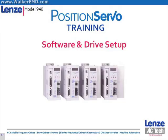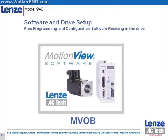In this section, we will discuss the Motion View on Board (MVOB) programming software and the basic position servo drive configuration. Position servo drives feature Motion View on Board (MVOB) software. The MVOB software is a Java-based software package embedded within the drive. The user simply uploads the programming software out of the drive onto their PC using a standard web browser.